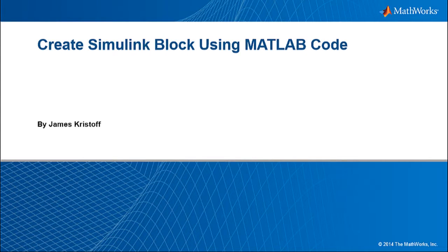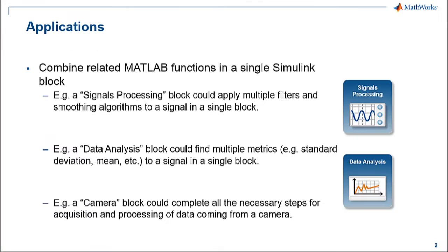In this video, we are going to create a Simulink block using MATLAB code. The process we will use can create a Simulink block from MATLAB functions alone, or from both MATLAB functions and functions written in C. There are many applications which can benefit from the creation of custom blocks, such as signal processing, data analysis, and communicating with hardware.